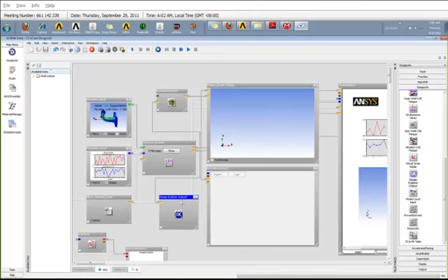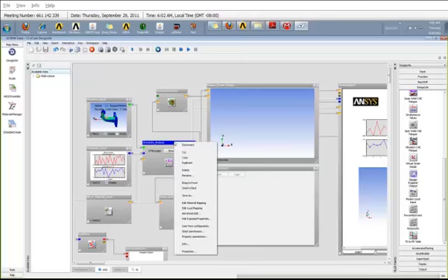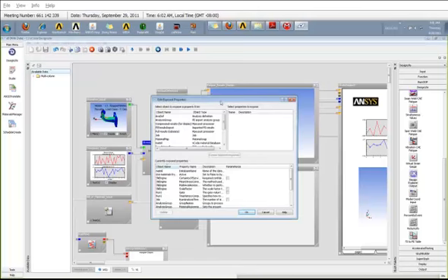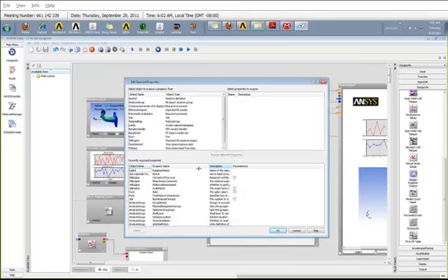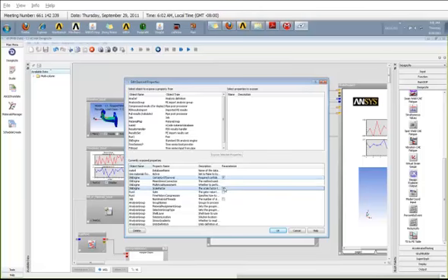In addition to the output that you can set, ANSYS DesignLife also gives you some parameters that you can parameterize as input parameters. To do that, you do a right click on the stress life analysis, and select Edit Expose Properties. Let's go ahead and select that one. In this Edit Expose Properties, let me maximize the screen over here. It gives you a couple of options. One is certainty of survival. I can just click here to parameterize that. And it also gives you another option called scale factor, which I can also parameterize.